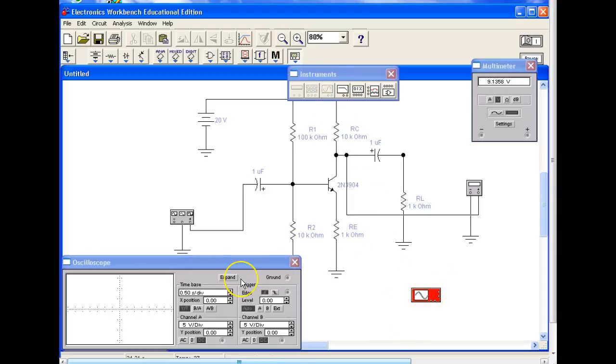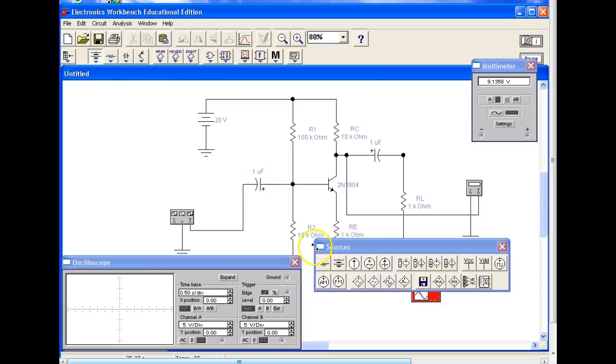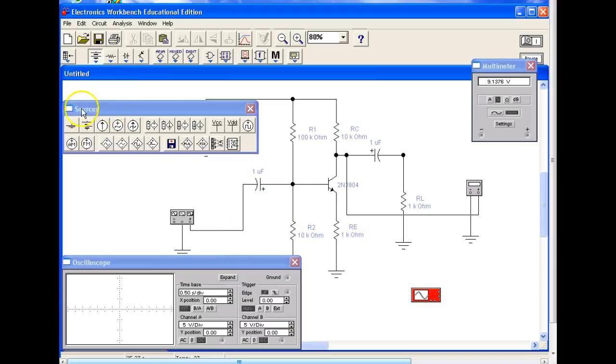So this is my oscilloscope. It's a dual, and this electronic workbench has a real problem synchronizing, so it's going to be hard for us to trigger this, I don't think. So here's my ground lead up at the top. So I'm going to connect a ground, a common, to my oscilloscope. By the way, this guy uses the ground symbol for everything, and it connects right here.